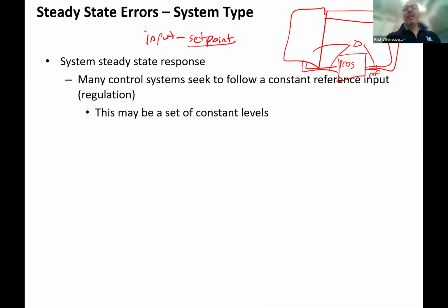This can get more complicated though, because temperature can really mess things up. If the temperature of the process can vary widely, you also have to feed that into your pressure measurement so it can do some correction. But the thing you can't correct, or at least I've never seen it corrected, is the material inside. If the material inside is 80% clean water and 20% some other stuff, but it could vary between 70 and 90, then your level can get all screwed up. So you can't adjust for the density of the material. I just have never seen that.